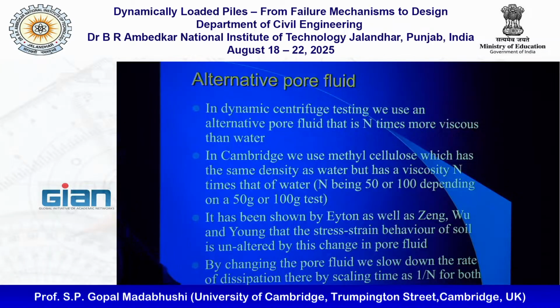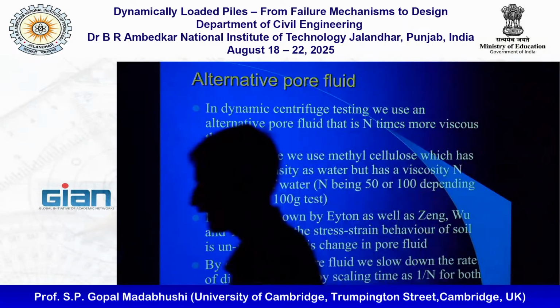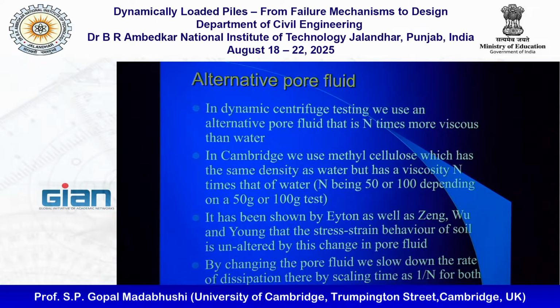So by now changing the pore fluid, what we have done is the permeability you were mentioning earlier is now reduced by a factor of n, because permeability of soil depends on not just the gaps in between the soil grains, it also depends on the pore fluid.